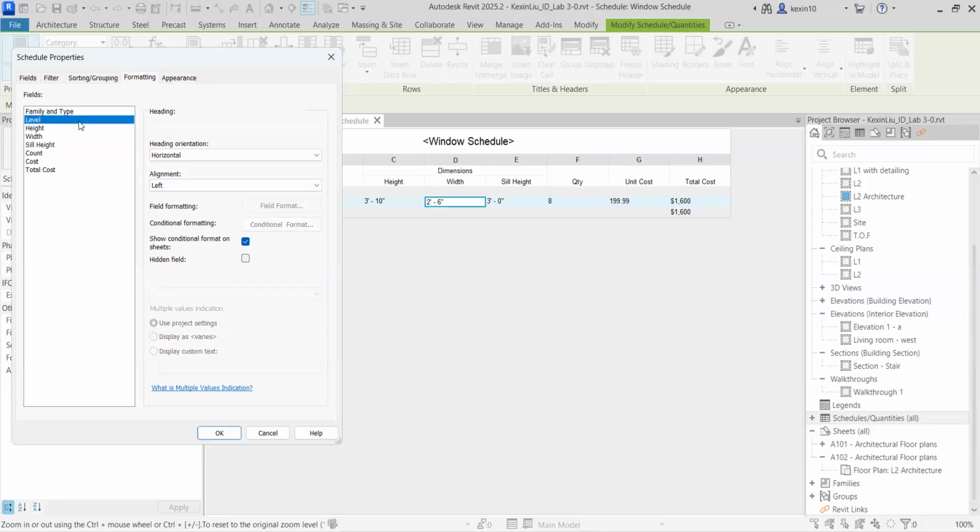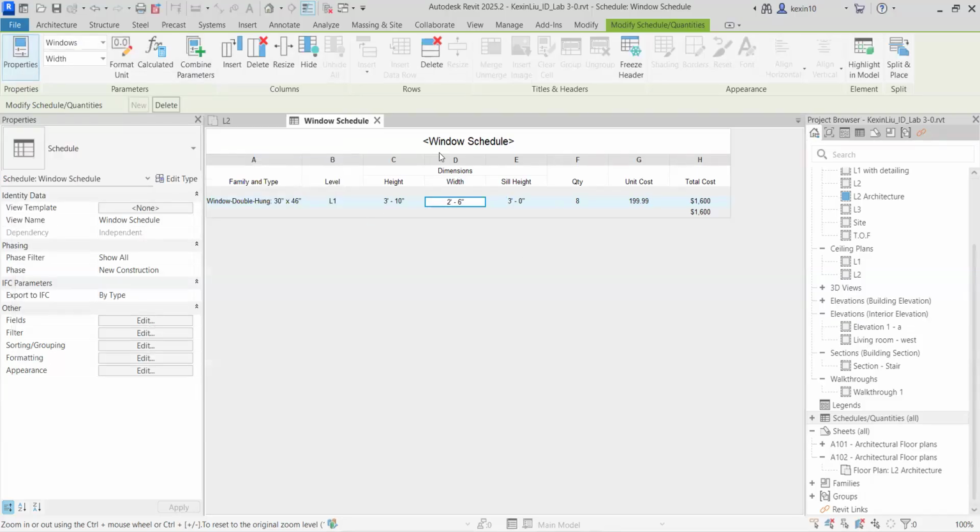You can use Shift and accept the family type. Choose all the things except the family type and set the alignment to center. Okay, you can pay attention to here and you can see the changes. So let's click OK. And now they are in center.